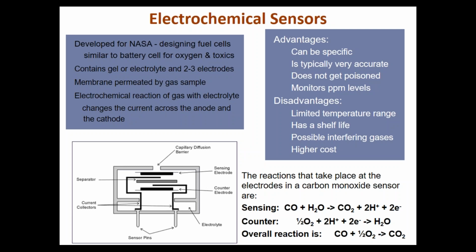The other thing is there are some interfering gases that could affect an electrochemical cell. So you have to be very aware of other gases or vapors in your environment that might give you false alarms when using electrochemical technology. It is very specific, or can be very specific, and that's the beauty of an electrochemical over a more generic, well, we talked about the solid state sensors.